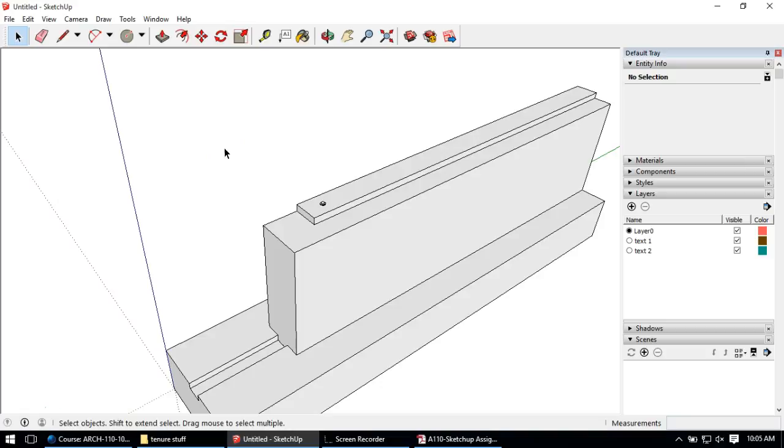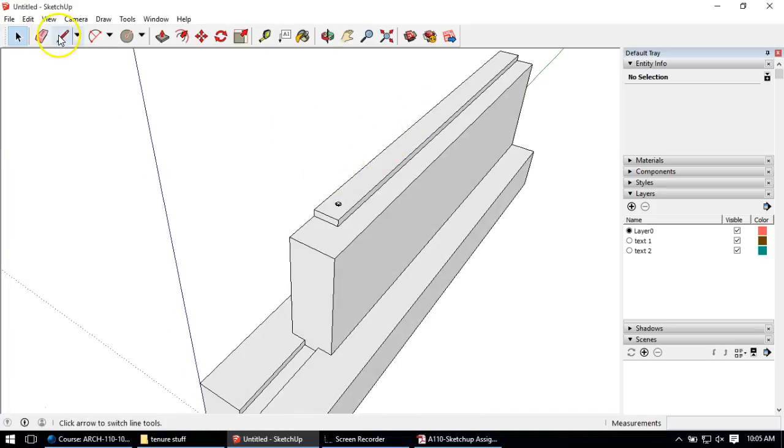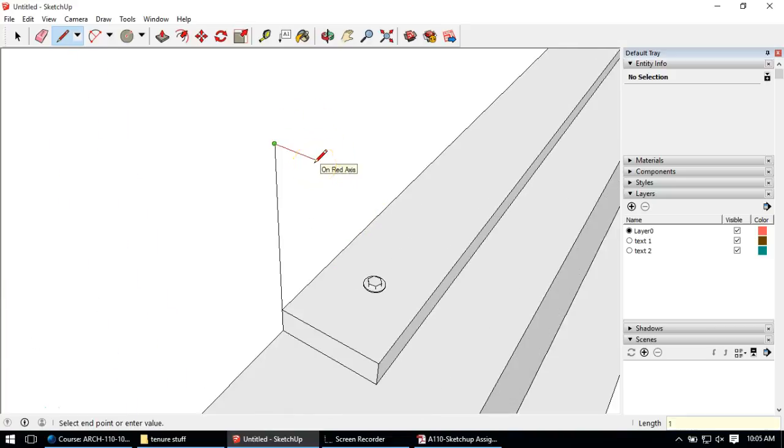Here we go. Okay, the next thing we are going to do is we can start with the joists. I just want to make sure I get the right size, and they're 2x10s. So this front one's going to be a 2x10 as well. So I'll start there. A 10 is really 9 1/4 inches, 9.25. It's going to come over 1.5. Making sure I see the red axis line, and I want to make sure I see the blue one to go down and come across.